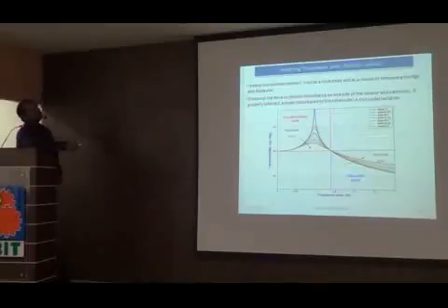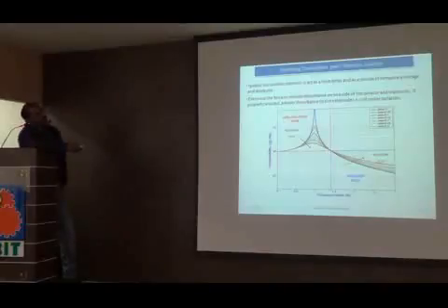And for this you should refer to the transmissibility curve. Why? Because one should know the zone of isolation. If you see the transmissibility curve of any system subjected to base excitation, you can see that beyond root 2 times the natural frequency, the transmissibility falls down.